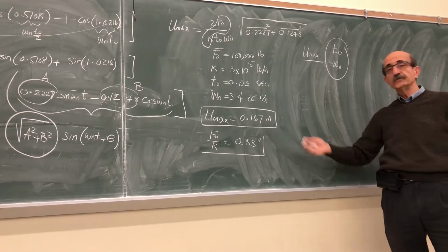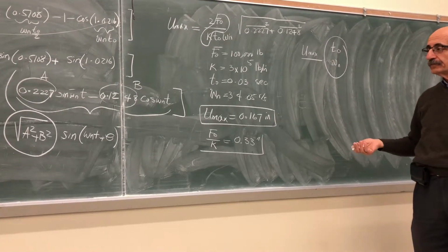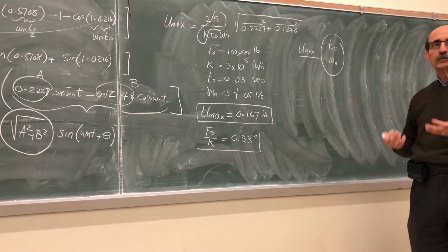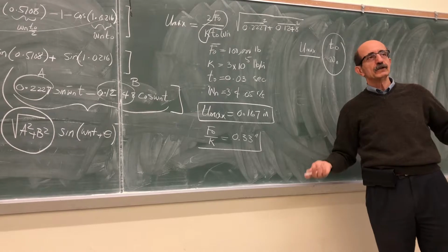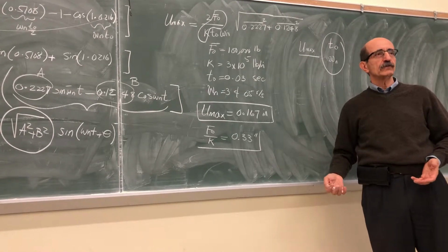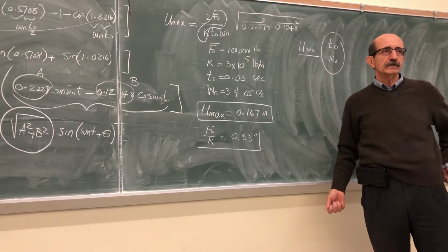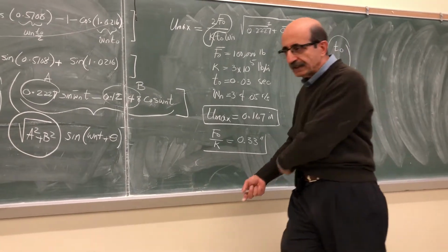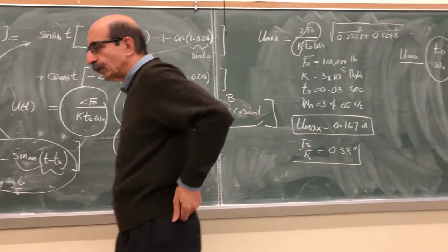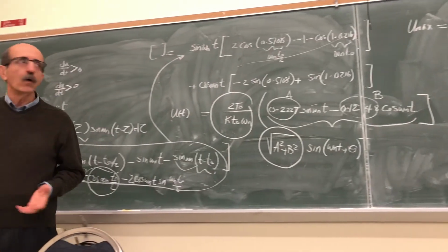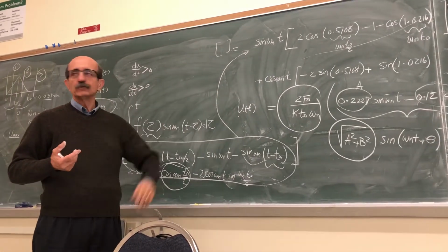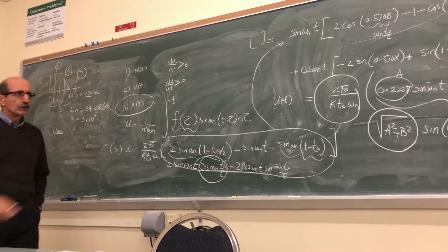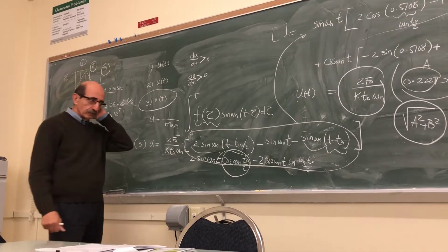The point is that contrary to the common assumption or perception that if you have dynamic loading, let's take a factor of safety of 2, that's just not right. That factor of 2 is only valid when you have impact loading. So for other types of loading, you really need to evaluate the maximum value. And that was really the main reason for going over this example.